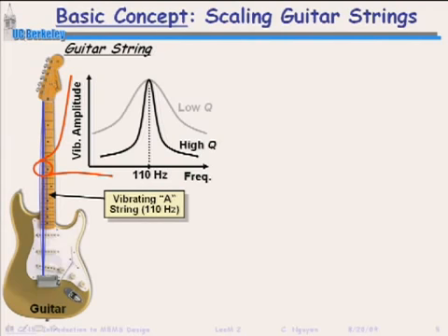And you need a device that can do something like what this is showing here. It can select a certain frequency and reject all other frequencies, because that in the end is what your cell phone is doing as well. It's basically trying to receive a very specific frequency, which you're communicating with someone else on. But then there's, of course, many other conversations happening at the same time, and those other conversations are happening at different frequencies. And so what you need to do is reject those frequencies where the other conversations are happening and collect only yours. And that's why you need to have these tuned frequency circuits like this.